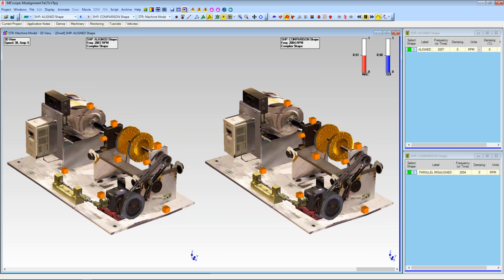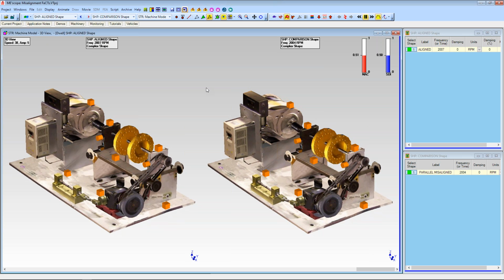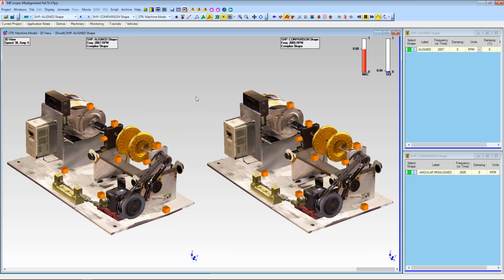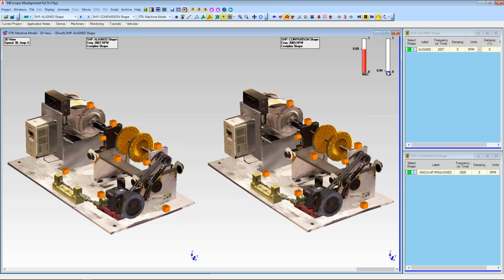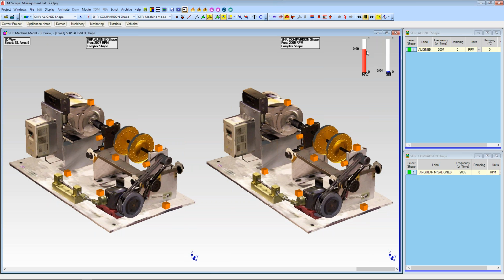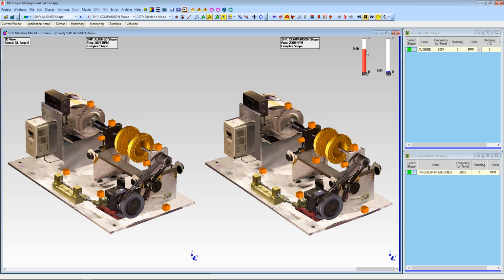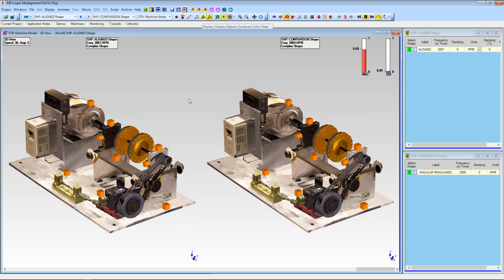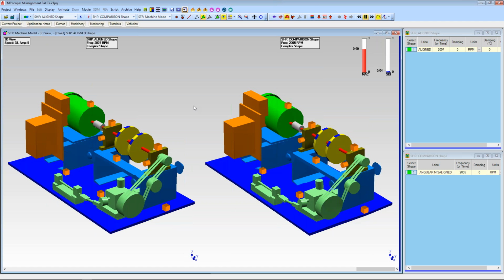So even though the pictures don't look a whole lot different, the metrics are telling us that these two ODSs are quite different. Now we're going to go over here and look at angular misalignment. SDI really dropped. MAC value not so much, but again, quite a difference in the ODS data.